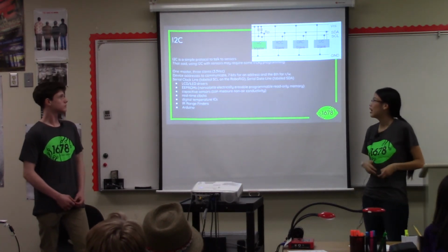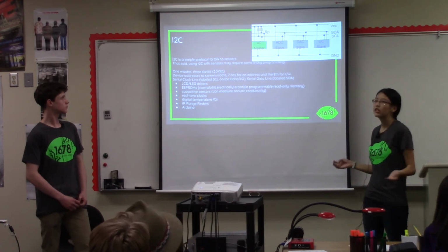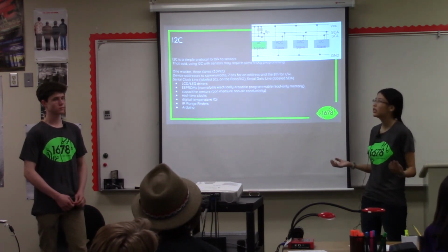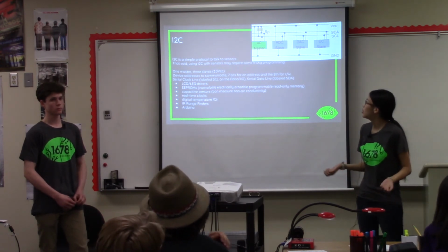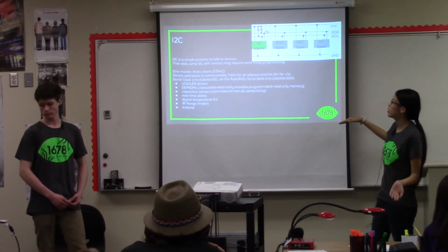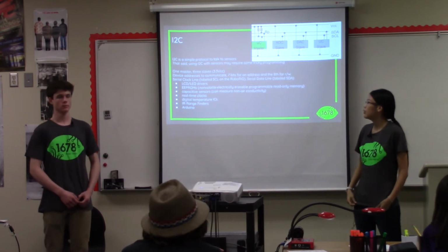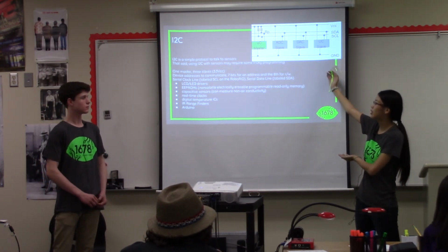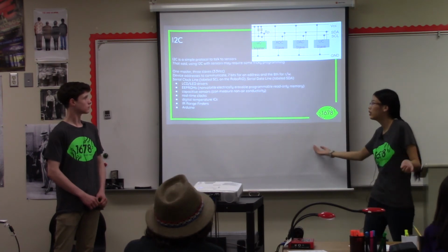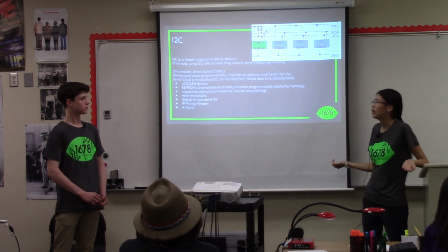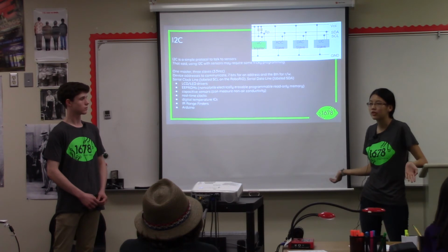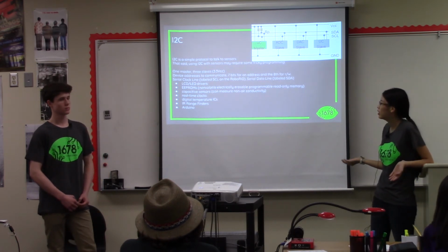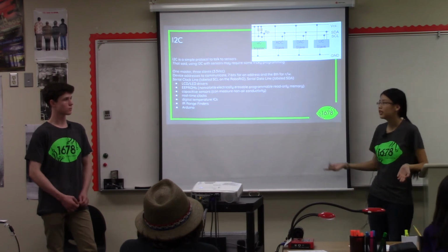Okay, so what is I squared C? I squared C is one of the main inputs on the roboRIO. It's not actually commonly used. 1670 doesn't use this. But I2C is another master-slave relationship. So what happens is that the master communicates with these slaves, and the slaves send back their data depending on the clock. This is normally used for example, like LED drivers, or maybe some gyros use this, which you can attach onto the roboRIO. But again, it's not commonly used in FRC.